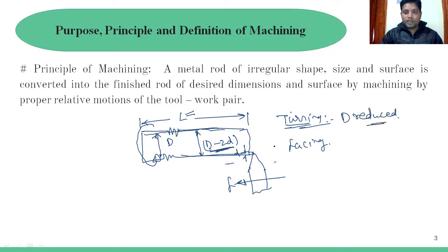Okay, in case of turning, now we are doing facing. So in facing, generally we have to keep the single point cutting tool over here, or in this direction also we can keep. This is rotating, and we provide the feed to this single point cutting tool towards this direction, downwards. So up to the center of the material has been removed from this cross section.